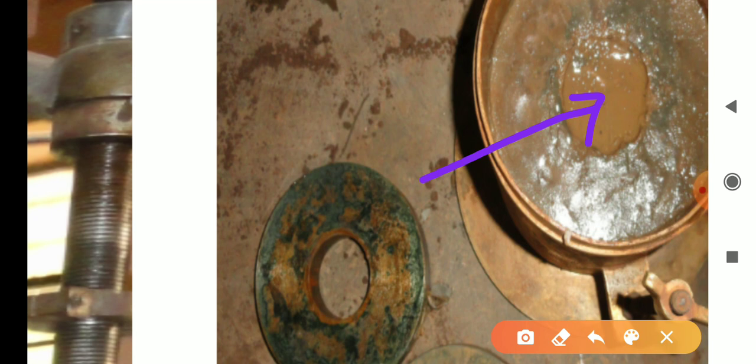In that case, we will get more volumetric changes or volume changes. So in that we will get more penetration. If we get more penetration or more impression, the CBR percentage is less. If we get less penetration, the CBR percentage is more. For example, I will give an example.